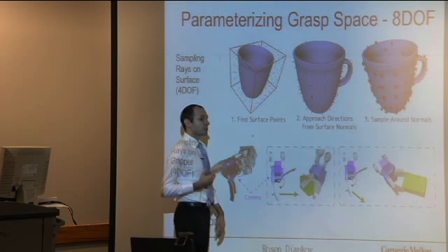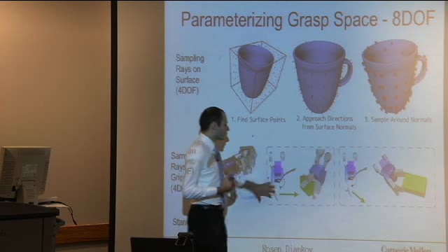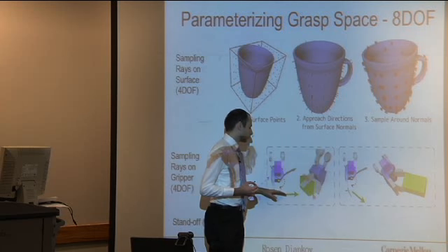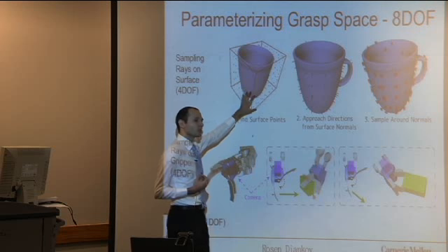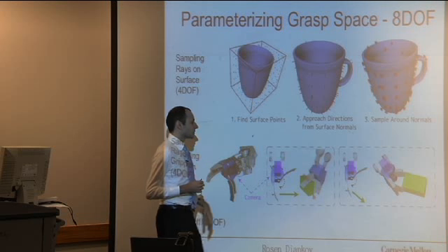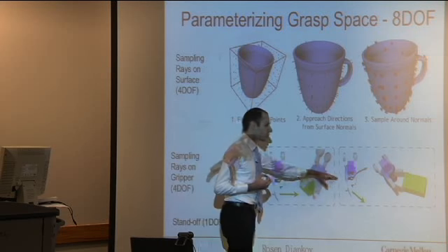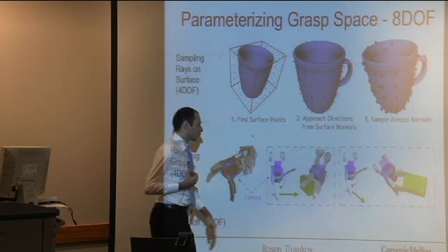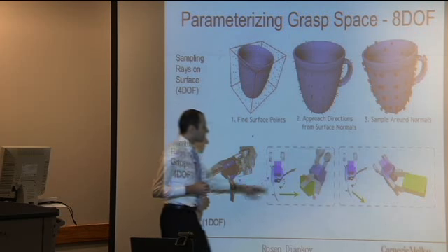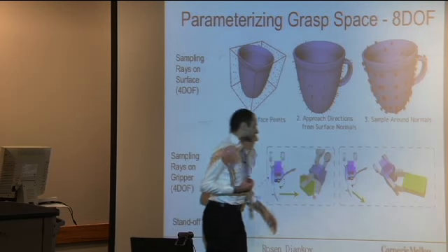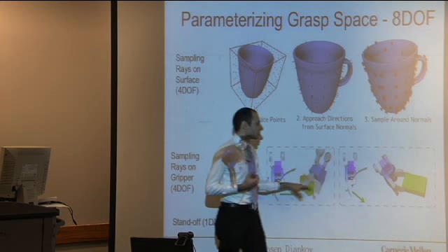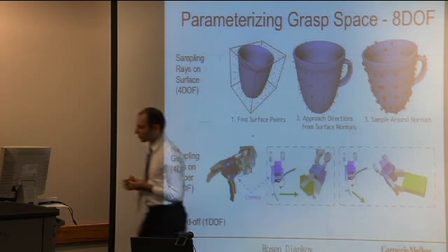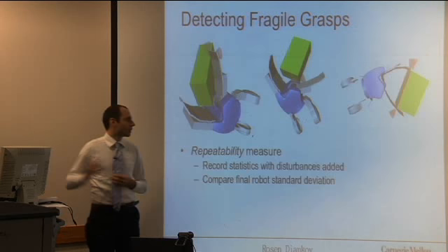Generally, for really good anthropomorphic hands, you can fix the ray on the gripper coordinate system and just worry about sampling the surface really well here. However, for 1 degree of freedom hands, like this one here for the HRP2 humanoid, changing the direction of the ray can change the grasp from really powerful power grasps to pinch grasps. So we show its importance there.